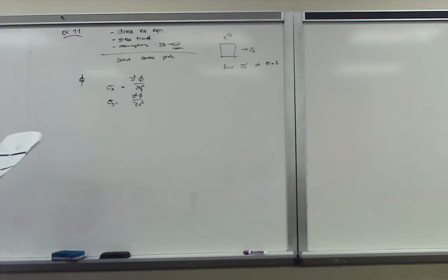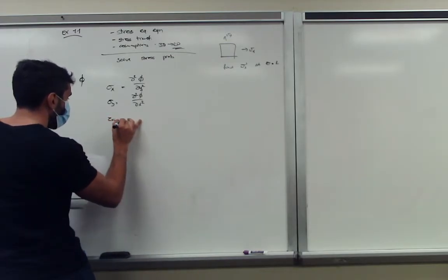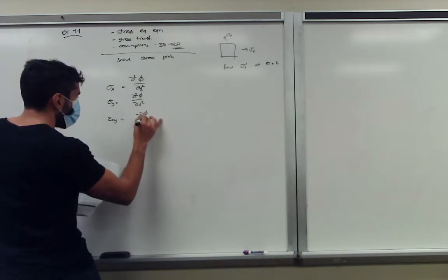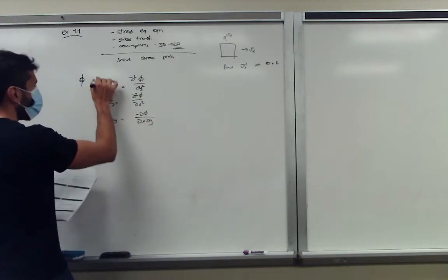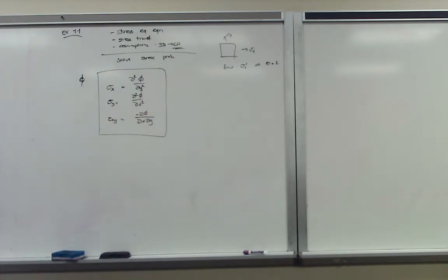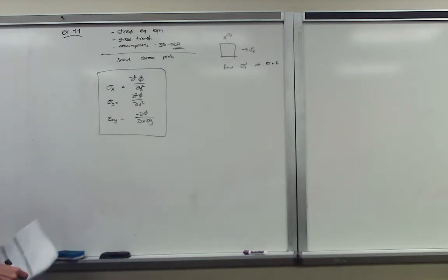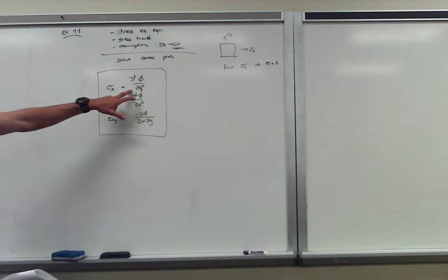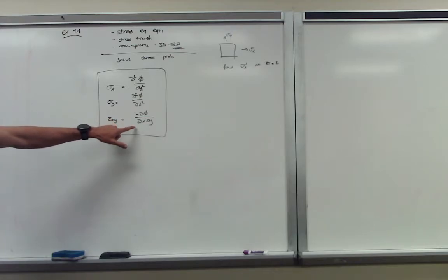And my tau xy is given as the negative of the derivative of the function with respect to both x and y. He needed a function such that if I differentiate twice with y, I get my stress in x. If I differentiate twice with x, I get my stress in y. If I differentiate with x and y and take the negative, I get my tau xy.